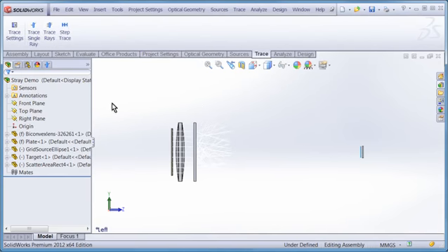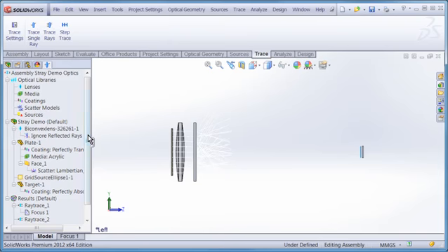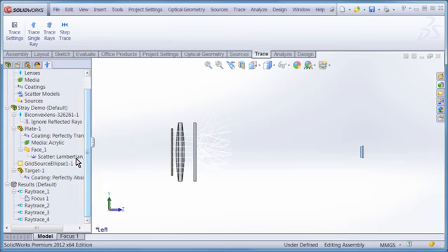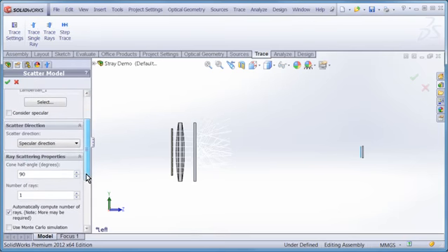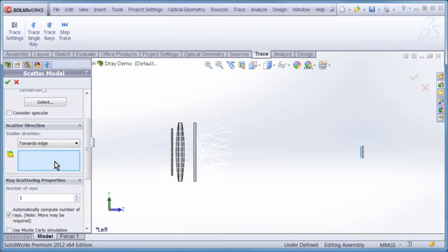The other thing we need to do after changing the project settings is we actually have to modify our definition of our scatterer. So let me come over into my Optics Manager, and I'm going to select the scatter face right here, right-click and then Edit, and instead of scattering light into the full hemisphere relative to the specular light, what we're going to do is scatter towards our defined importance edge.